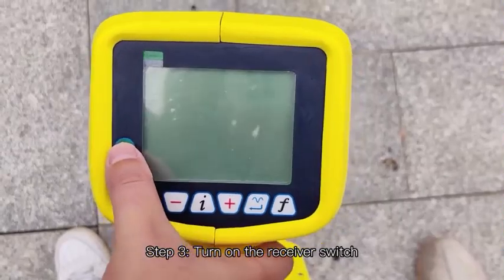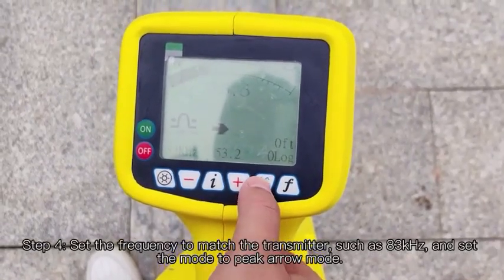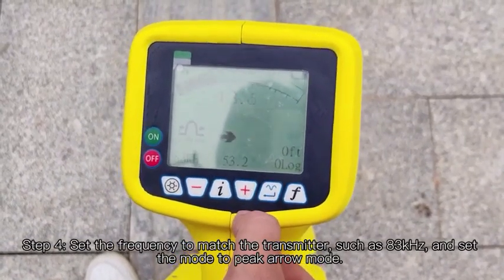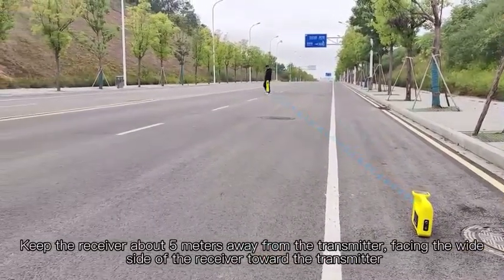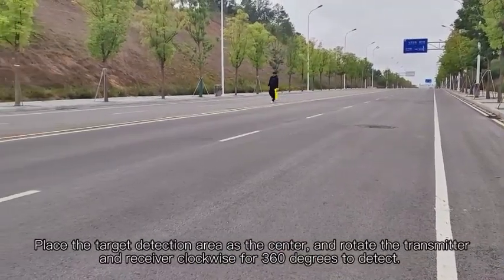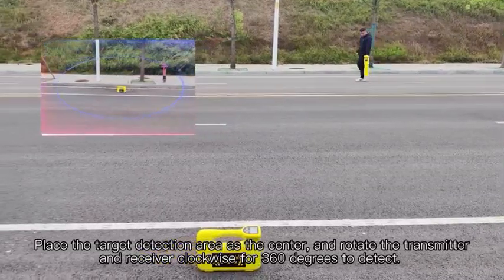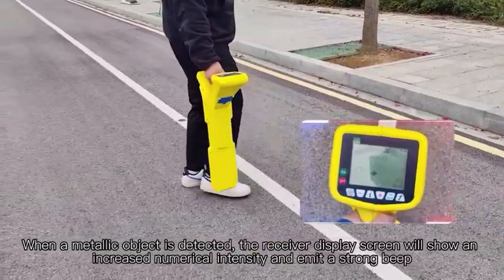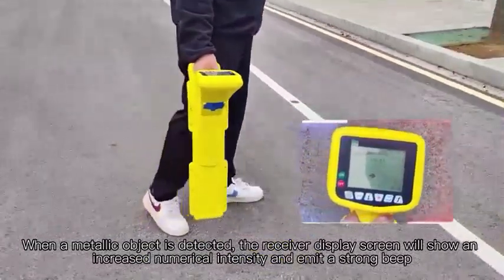Step 3. Turn on the receiver switch. Step 4. Set the frequency to match the transmitter, such as 83 kHz, and set the mode to peak arrow mode. Keep the receiver about 5 meters away from the transmitter, facing the wide side of the receiver toward the transmitter. Place the target detection area as the center, and rotate the transmitter and receiver clockwise for 360 degrees to detect. When a metallic object is detected, the receiver display screen will show an increased numerical intensity and emit a strong beep.